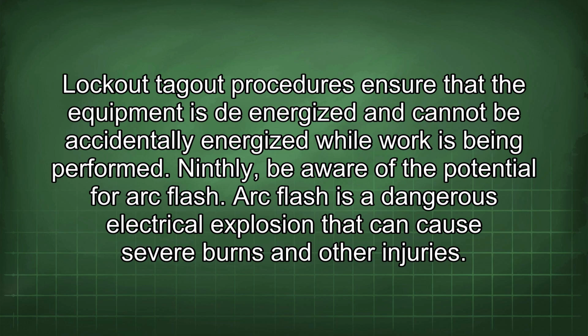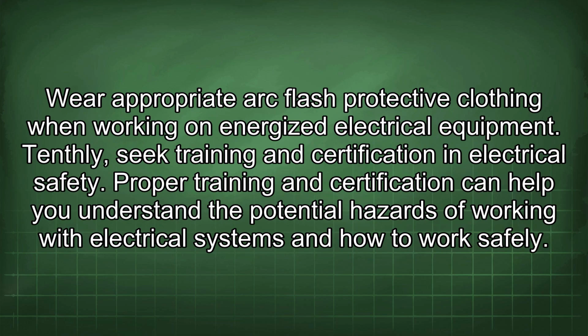Ninthly, be aware of the potential for arc flash. Arc flash is a dangerous electrical explosion that can cause severe burns and other injuries. Wear appropriate arc flash protective clothing when working on energized electrical equipment. Tenthly, seek training and certification in electrical safety. Proper training and certification can help you understand the potential hazards of working with electrical systems and how to work safely.